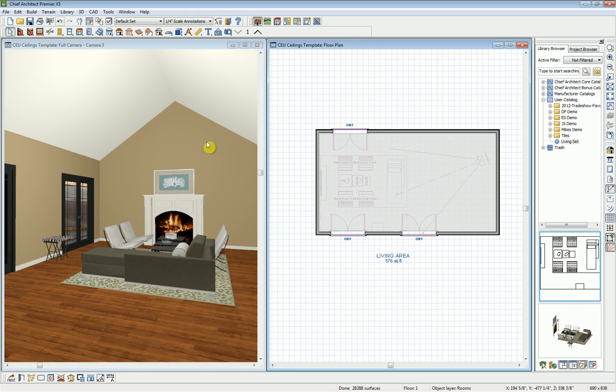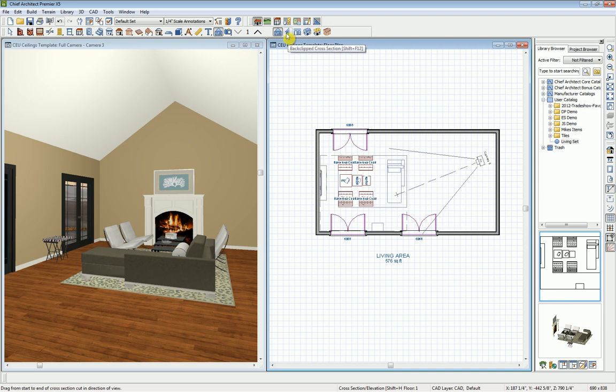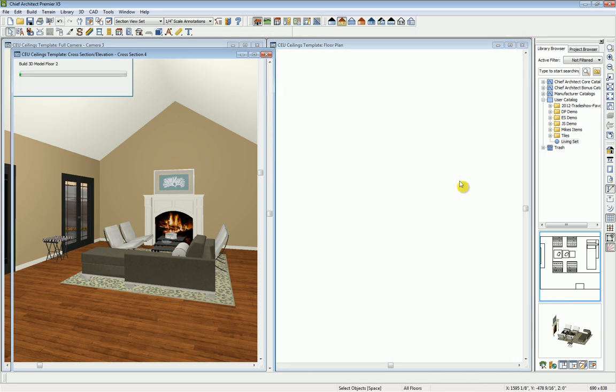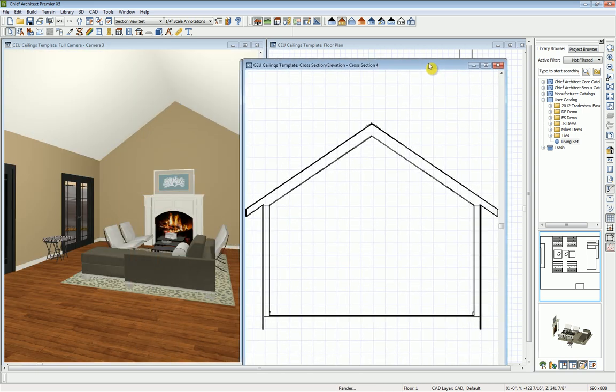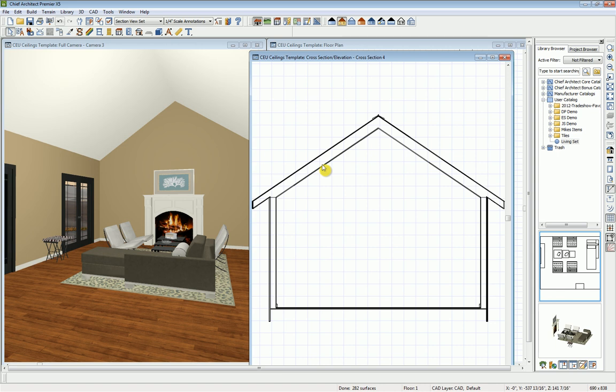Now the ceiling that we get is just following the rafters above. So I'm going to pull a new camera view just so I can illustrate this to you. And again, this is nice with a client because they may not understand what it looks like when you have your ceiling following rafters above. So here's the ceiling plane that's following our framing above. And some of the issues we run into, and you can graphically show this to your client, is that we have trouble perhaps meeting the insulation requirements that are now in attic spaces of R30 or what have you.